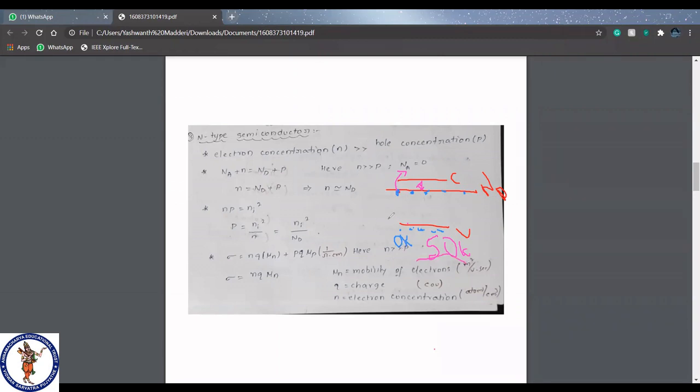The same thing is observed in p-type, but there the electron moves to the acceptor level, whereas here the electrons move to the conduction band. Similarly, at 300 kelvins the same story repeats, but the electron can jump from here to here or here to here as well. But in most cases, the electron will jump from the donor level to the conduction band only.